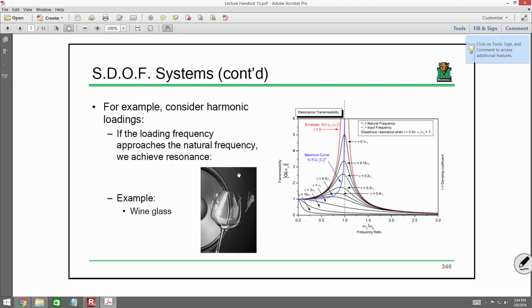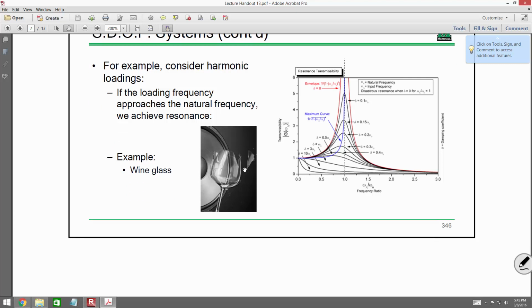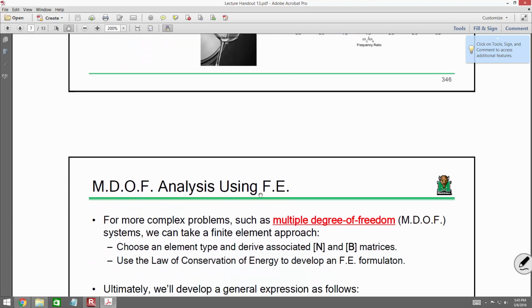If you produce an auditory vibratory wave onto that glass and match the frequency, the glass's deflection will shoot through the roof. It has no stiffness to resist those loads, and it'll shatter. Okay? That's what's happening. That's what resonance is. Okay? Everybody's seen that before, right? Make sense? Okay, so just you know, some larger issues so that you all know what's going on.